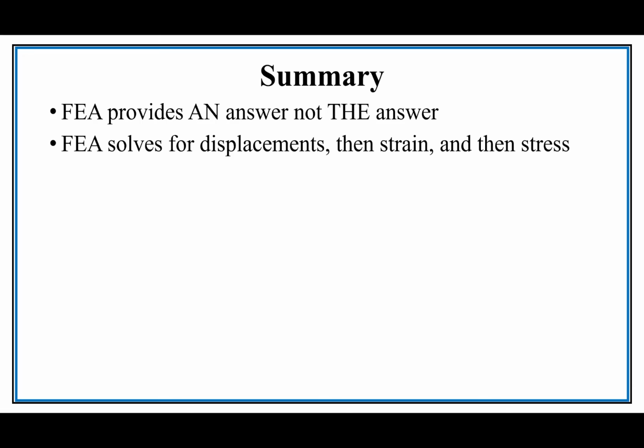Note that FEA solves for displacements. The topic here today is deflections, and that's a good reason for that, because that's what FEA is really doing. It can get the strains and thereby the stresses, and so we often use stress most often, and we associate it as a tool to find stresses, but what it does better than finding stresses is it finds displacements. And when we're talking about convergence, it converges to displacements much faster than it converges to stresses.